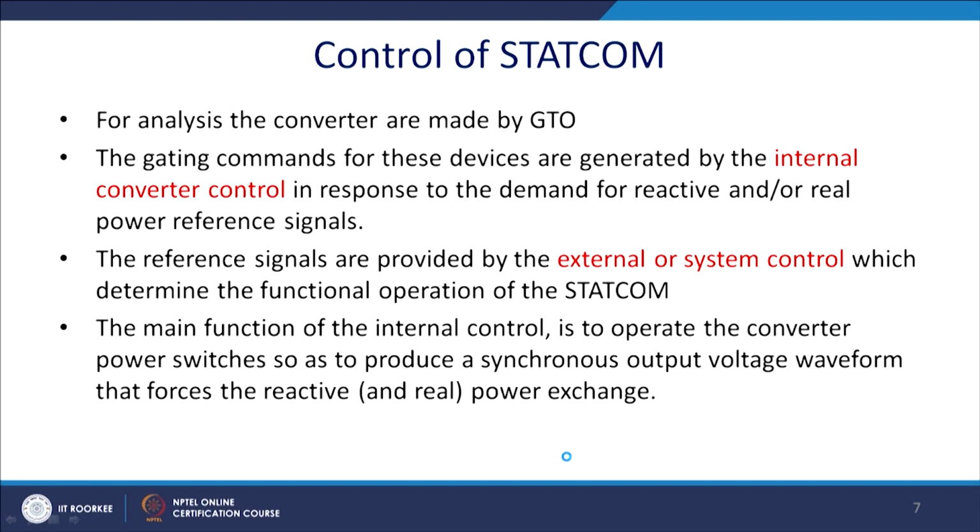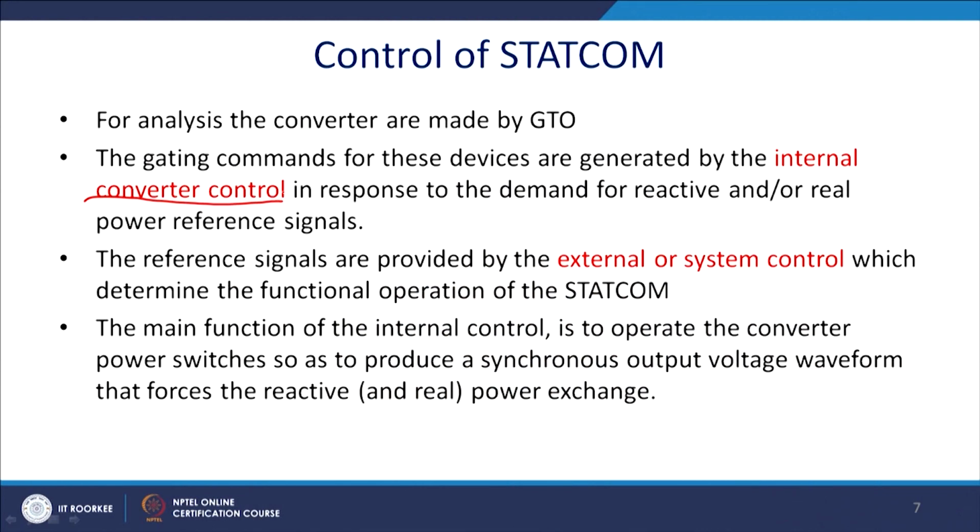For analysis of the controller, we consider that these devices are made of GTO because they require fully controlled devices, and maybe for the lower rating we can use IGBT. The gating commands of these devices are generated by the internal converter control in response to the demand of the reactive or the real power generation.